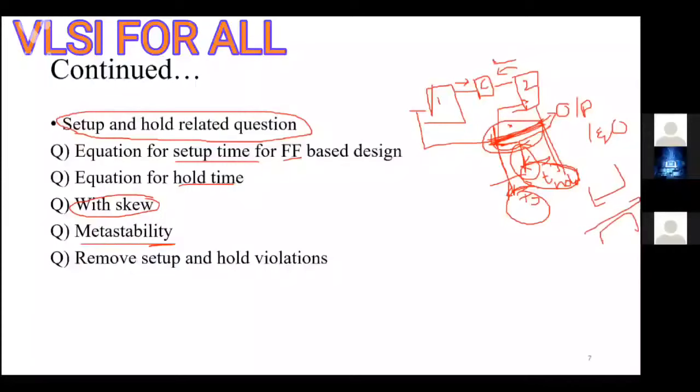There will be some tolerance for logic 0 as well as logic high. If the value is in between, then the digital circuit cannot predict it as 1 or 0. So this should be avoided for the circuit to work properly. The input should not change in the setup and hold window.